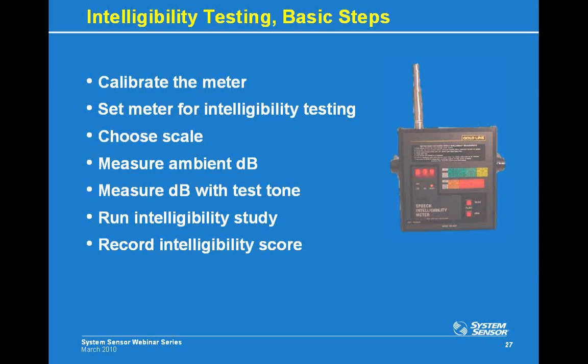After the calibration is complete, you'll check to ensure that your meter is in the proper test mode or setting, because most intelligibility meters also have the ability to do other types of acoustical testing. So it's important to ensure that it is in the right test mode. Also, make sure that the proper setting for the scale you're using is selected.